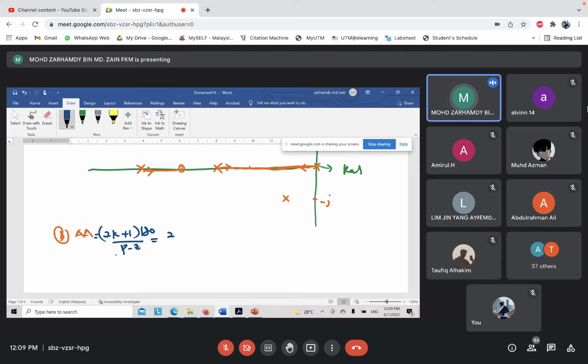In this case, we have 5 poles and 1 zero, so from here we have 4, which gives (2k plus 1) times 45. We substitute k equal to 0, 1, 2 and so on, increasing the number one by one until 360 degrees. After 360 degrees, they will go back to the previous angle.